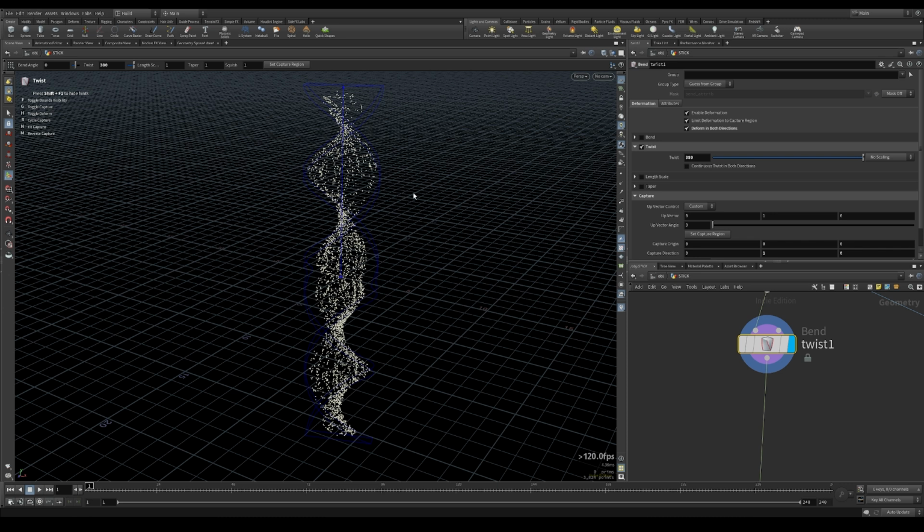What we want to do is basically to create an animated attribute that we'll use to scale all the deformation, and this attribute will be at the maximum value at the start, so the stick will be completely shattered and deformed, and then we will decrease to 0, so we will have the original points.